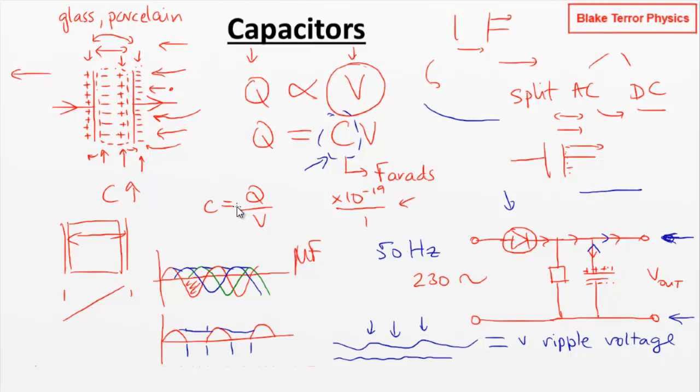It could be that you put a capacitor inside a fuel tank. If you've got some fuel level which is partly covering the capacitor, then how deep the capacitor is into the fuel will determine what value of C we're getting, and the capacitance changes accordingly. Again, we can pick that up in a sensing circuit. You get capacitors in touch screens.